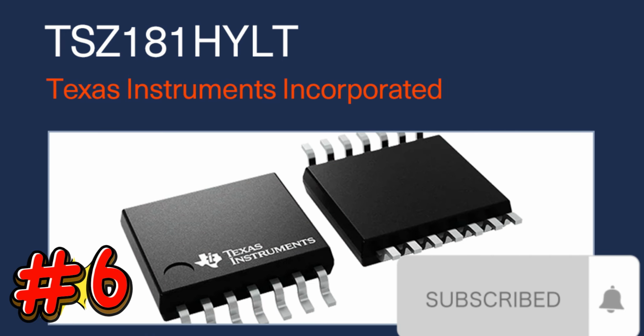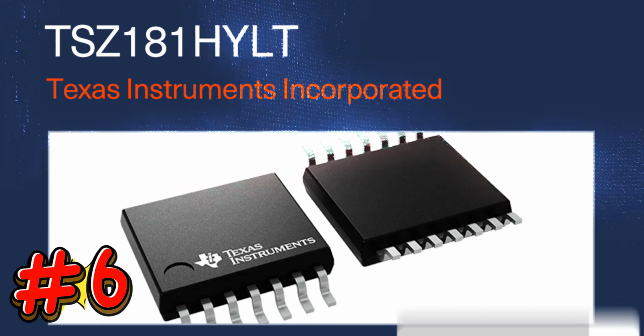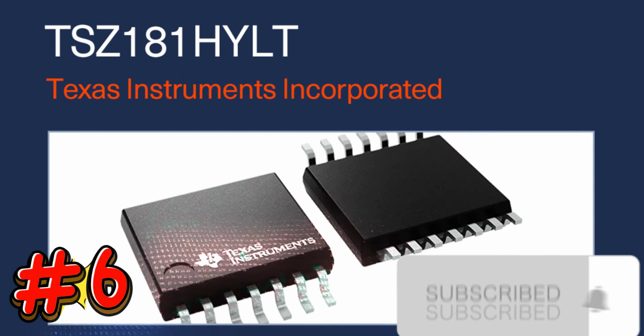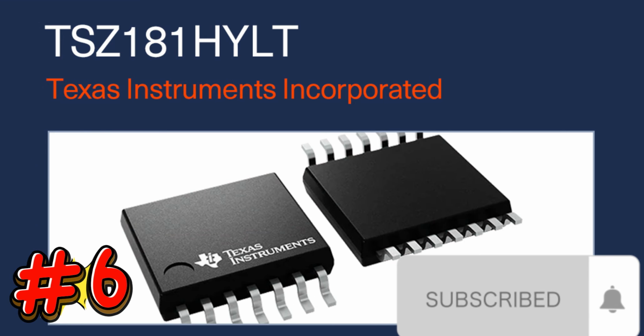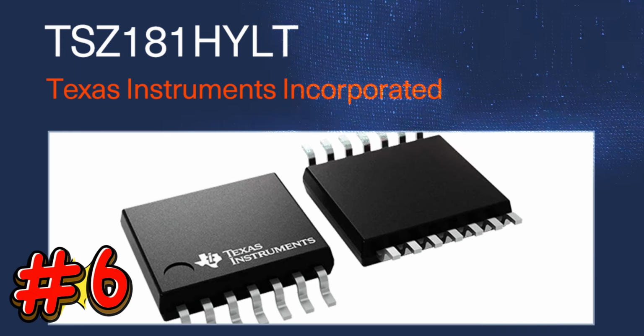Operating from split supply is possible when the difference between the two supplies is 3 volts to 36 volts for B version devices, 3 volts to 32 volts for V version devices, or 3 volts to 26 volts for all other devices. And VCC is at least 1.5 volts more positive than the input common mode voltage.